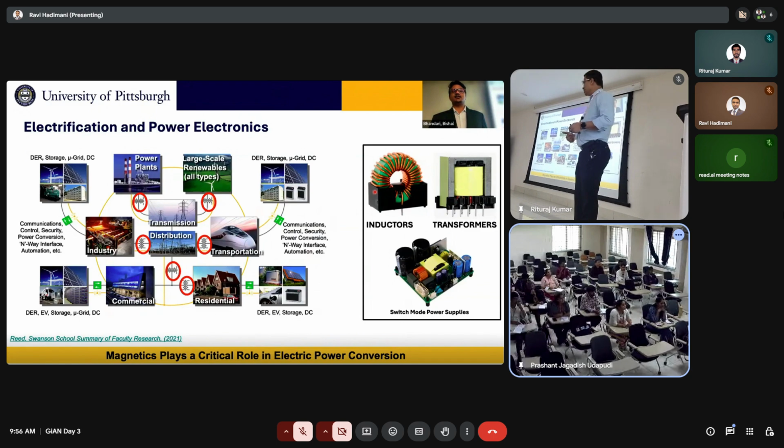The humming sound is because of another property called magnetostriction. So when you apply a magnetic field, a lot of the ferromagnetic materials change their dimension. Very small, in terms of ppm we're talking about, say 10 ppm, and that small change in dimension creates some sort of vibration, right? And that vibration is nothing but a sound, and that's why you hear that humming sound due to magnetostriction. So you have to reduce magnetostriction, you have to reduce coercivity, and you have to have high saturation so that you can work with high voltages.